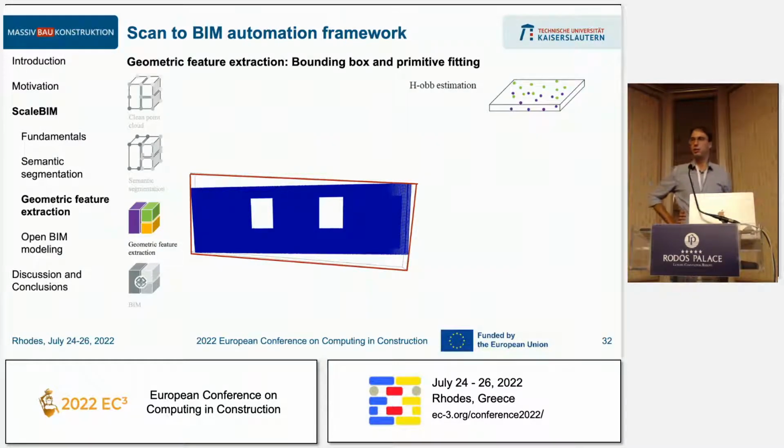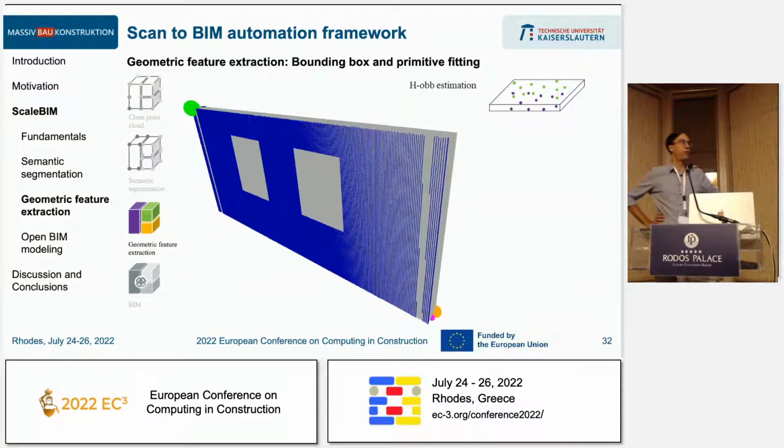However, with conventional implementations, we have faced some issues, as you can see here, because the known implementations of the oriented bounding box algorithms work pretty well on very heterogeneous shaped point clouds, like chunks of points, but they don't actually work very well on these square cuboid-ish objects that we encounter in buildings a lot. So we have developed our own methodology to assess the oriented bounding box of a point cloud.